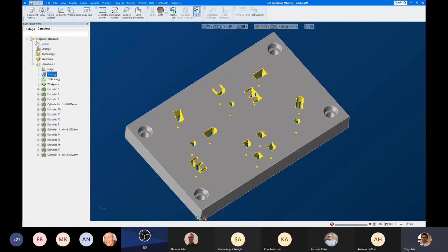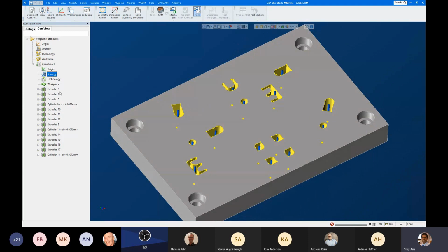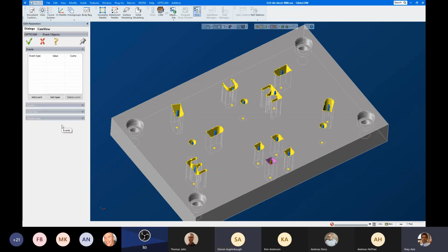And how do you set a taper for the shape? For example, I want 3 millimeter on the top to be vertical, and then a taper of 3 degrees. Right. Here I would pick what I want to set, and I would add a taper. You say what is the taper angle, and add a taper.